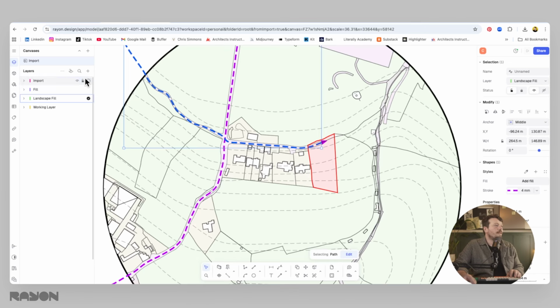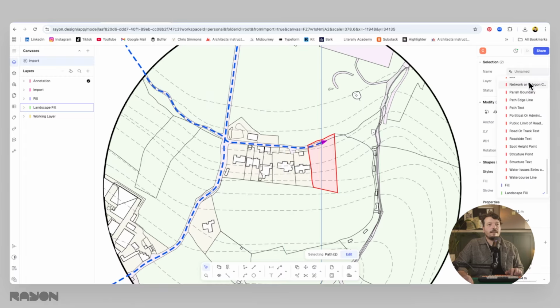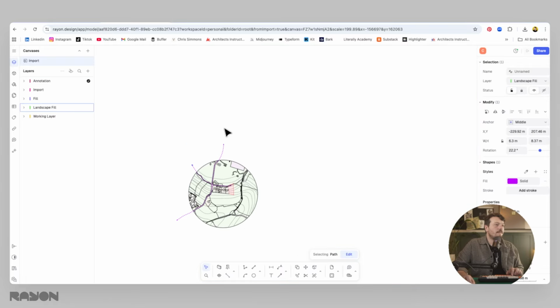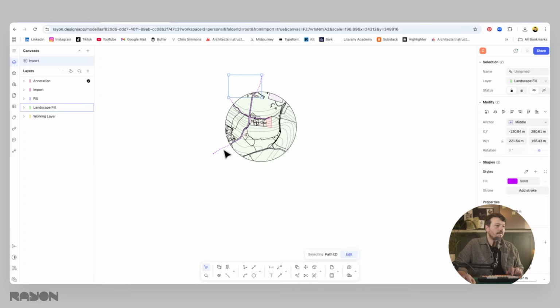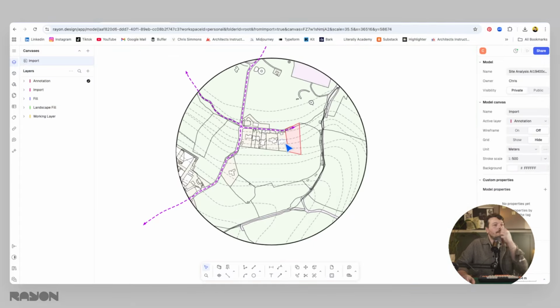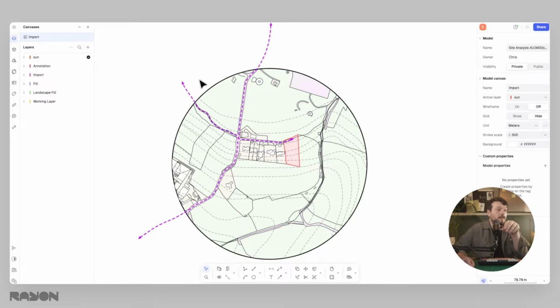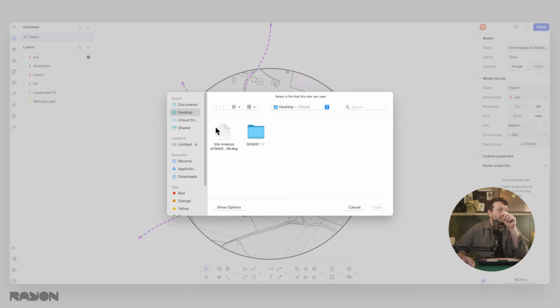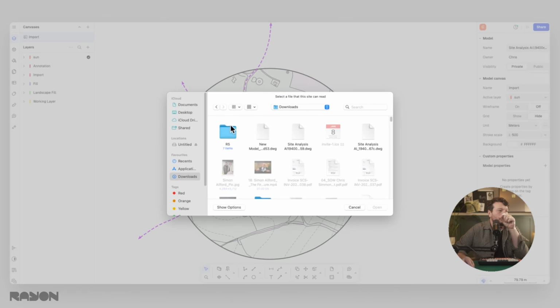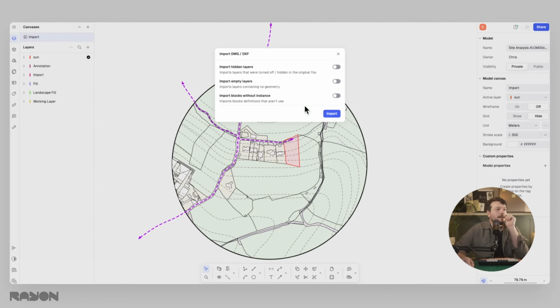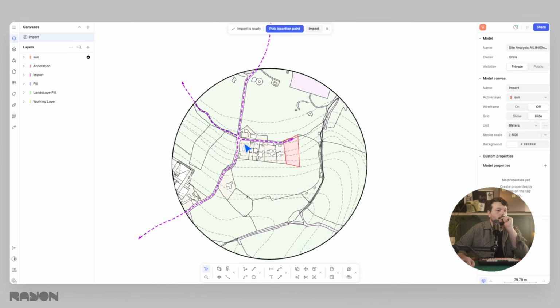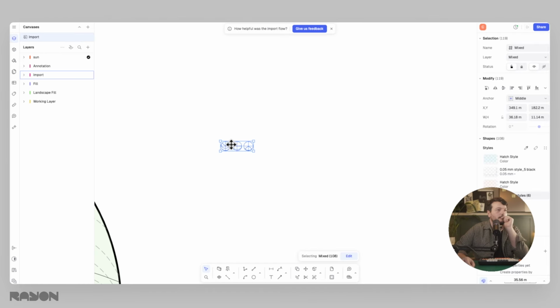Copy that down. Now I want to make sure that that is on a new layer, so it appears above everything on the drawing. So I'm going to call that annotation, for example, and then put those on that layer. Okay, make sure my arrowheads are on there as well. Perfect. Okay. Other factors that I'd want to consider on site are things like the environment. So I've been able to find the solar paths for this site, which I can import. Perfect. Let's bring those in.